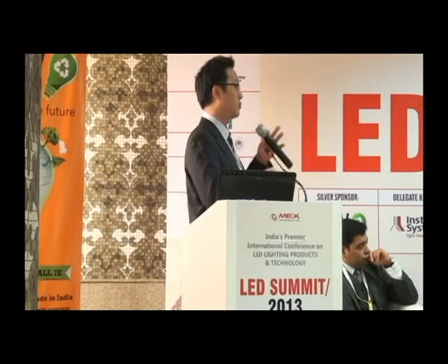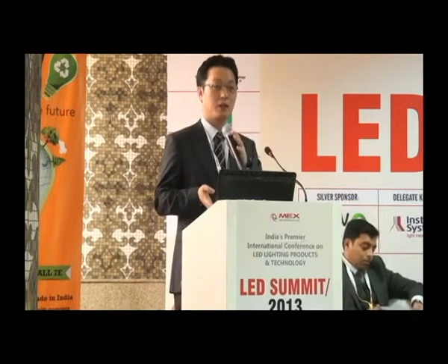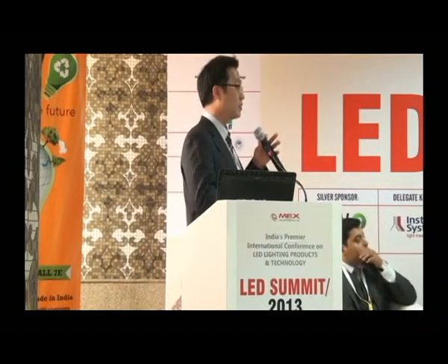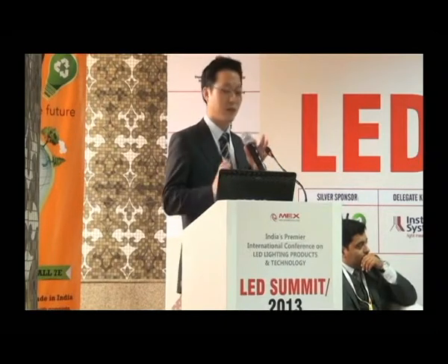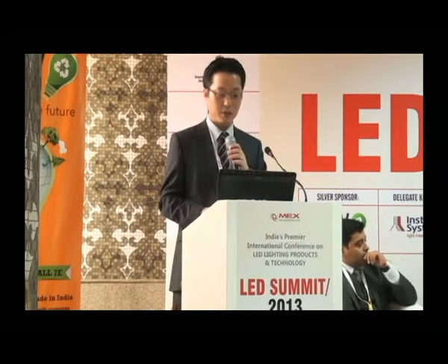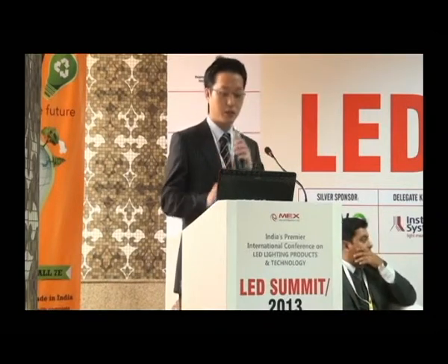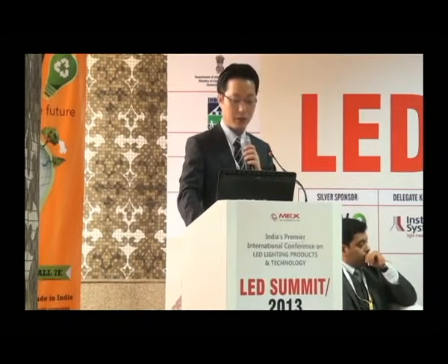Phenyl-based is good for sulfur gas blocking but very bad for heat aging. Methyl-based is very nice for heat aging, but bad for sulfur gas blocking. So the target of the silicone maker is combining such advantages together, to increase LED lighting performance in the LED industry.